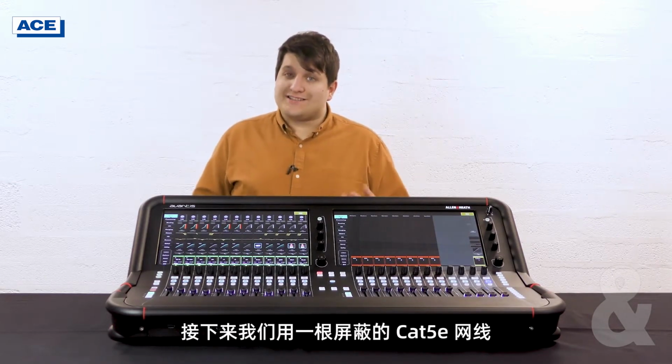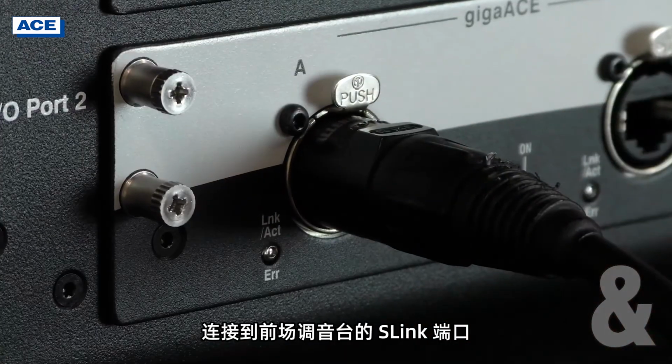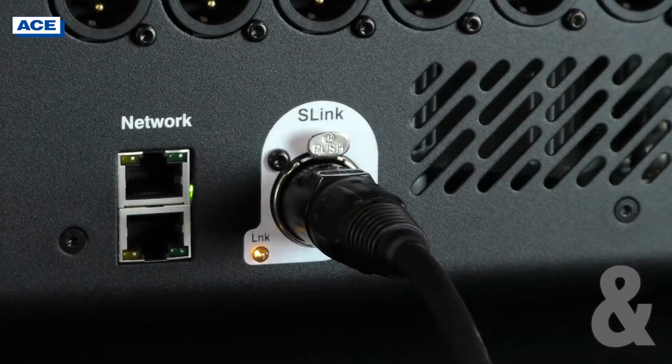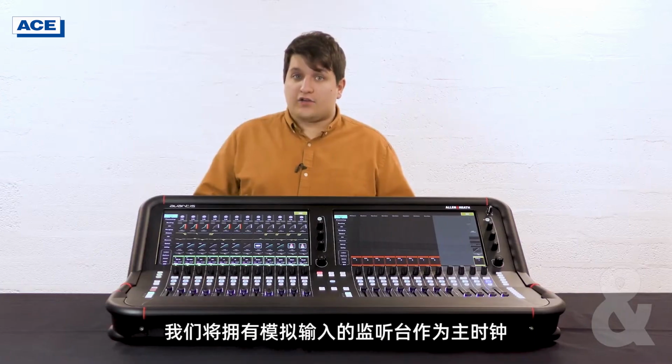We're going to connect a single piece of Cat5e shielded cable from the Gigarace A port of our monitor console to the S-Link port of our front of house console. One of the consoles must be designated as the clock master. In this case, it's going to be the console with the analog inputs, the monitor console.